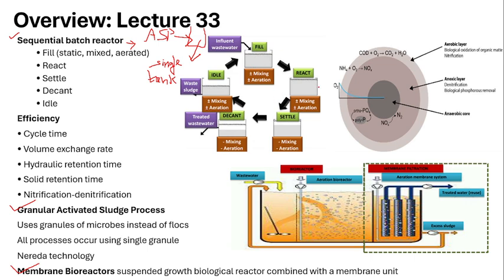Now the reaction will happen. During the reaction, the filling is stopped. No incoming wastewater is there in the react stage. The incoming wastewater is cut off here, but the mixing and aeration continue. We mix the water and again aerate the water so that the reaction will happen in the reactor.